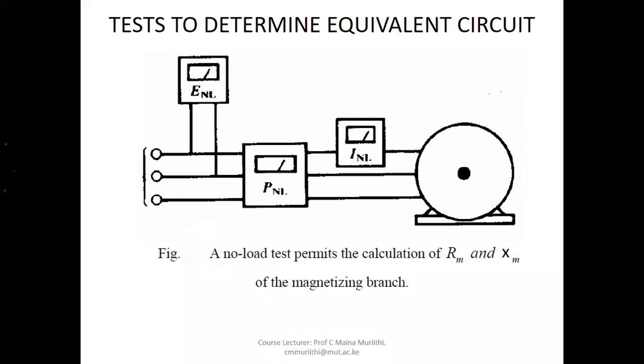Almost the same way as we did for transformers. There were 2 tests to determine the parameters of a transformer. So in the case of the induction machine, we have the no-load test and the locked rotor test.